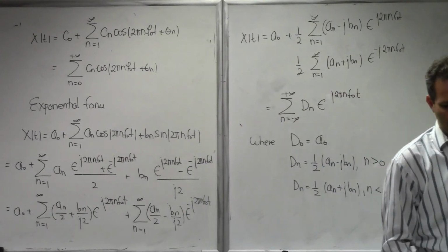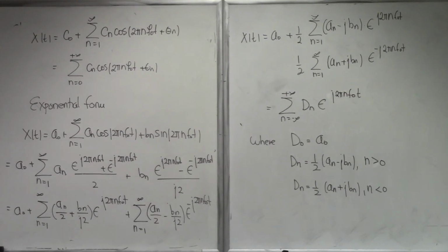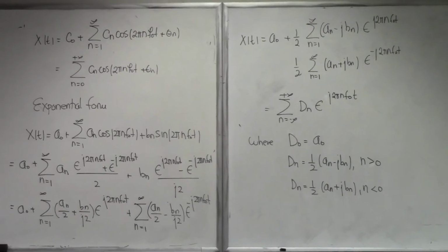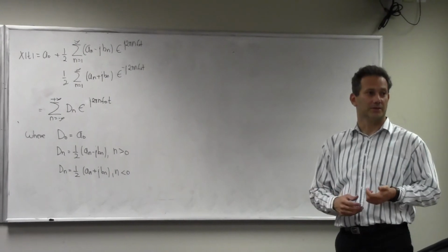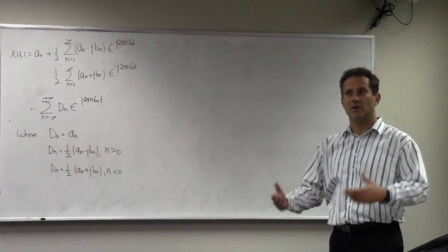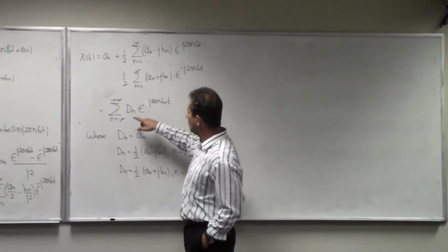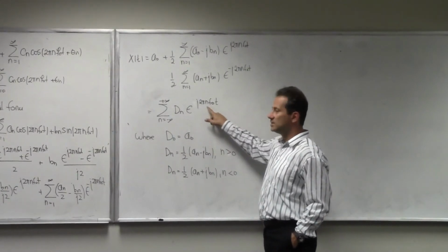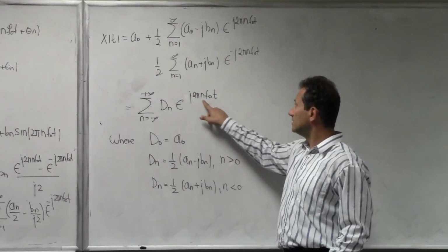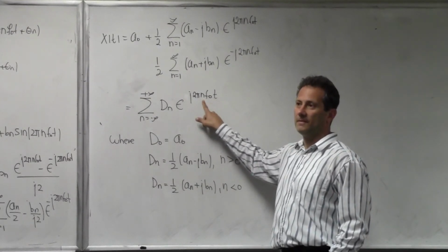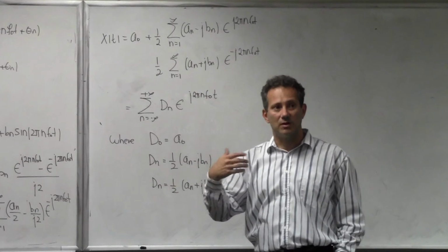So what is the conclusion here? Well, this is yet another insight. Remember, we said that we can build a periodic waveform out of the cosines. But then you say, wait a minute, cosine is built out of exponentials, right? Therefore, I can build the waveform just as an exponential. And I need all the exponentials that have frequencies that are integer multiples of the fundamental frequency. But in this case, this n can be both positive and negative. And that kind of introduces the notion of negative frequency. But there's really no negative frequency.